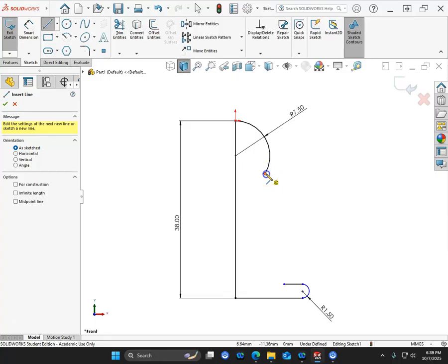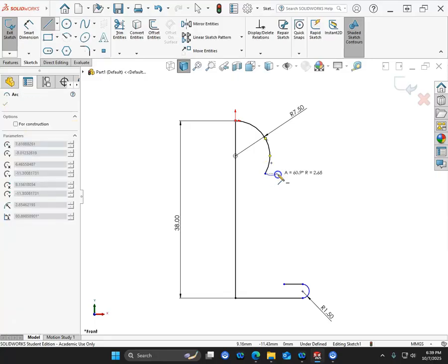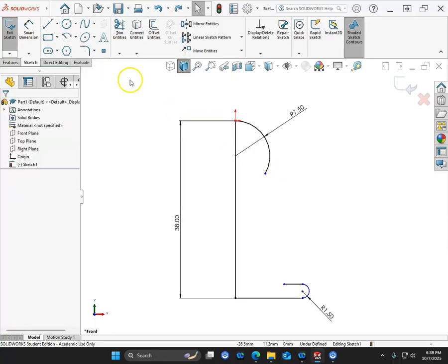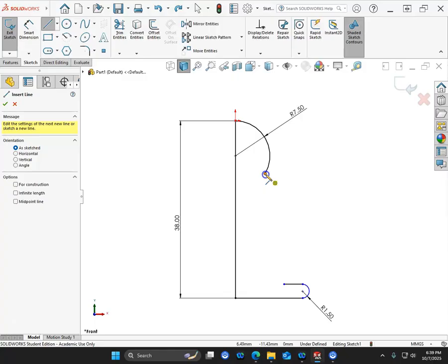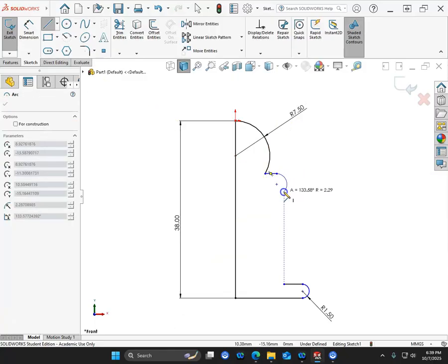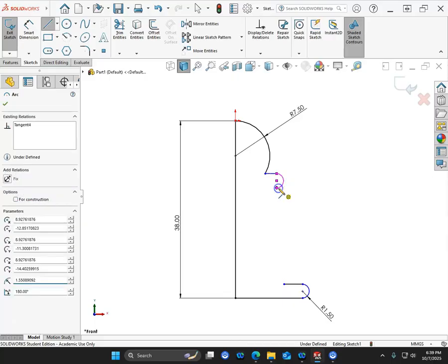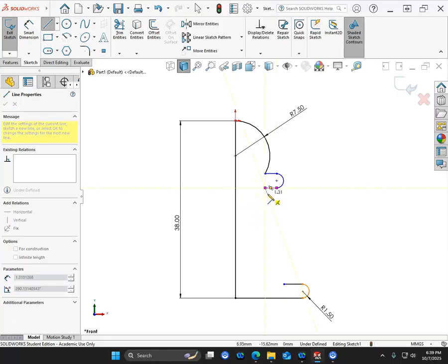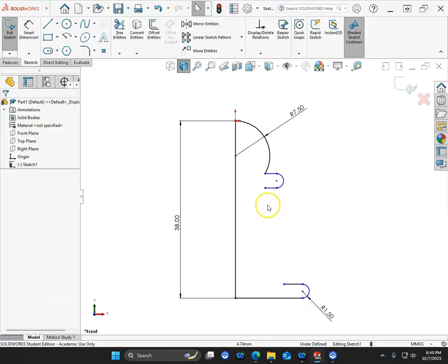We're going to utilize that continuous tangent arc. All right, so maybe not that way. So escape, control Z, because I moved back to the start point. So let's go back to this start point. Okay, my first line. And then there's going to be a little bit of a line. And now we're going to have to start watching for those inferences that maybe we want, maybe we don't want. So that one pulled up showing a vertical, but I don't see it.